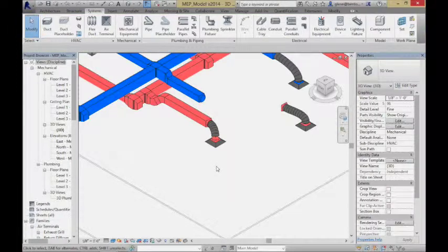Flexi-duct is actually a very useful thing. It's that stuff that almost looks like a dryer vent pipe, this flexible, hose-like, aluminum-covered flexible duct type system. It's really good because if there's any imprecision, it allows you to make tighter corners. It allows you to handle the fact that you may not be able to control right down to the last inch where this is, whereas these hard ducting systems really need to be controlled to get everything to match up. That sheet metal's fabricated down to the nearest inch. So it's not as efficient, so we tend not to use flexi-duct a whole lot, but as necessary, we put it in specific locations to make the connection.